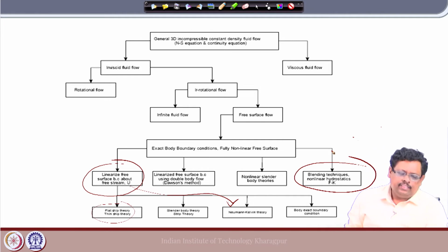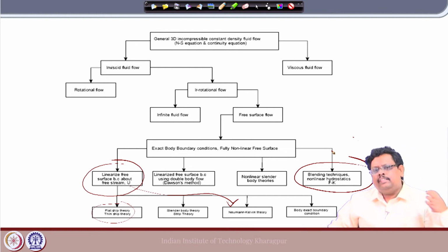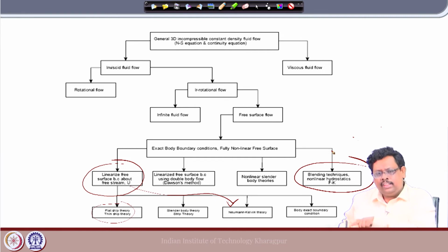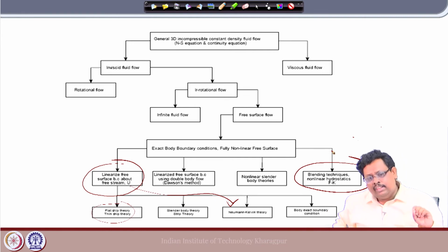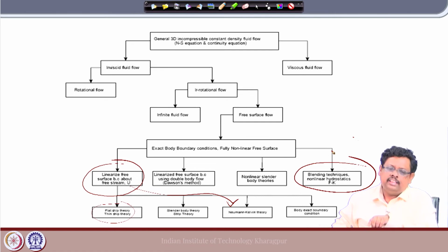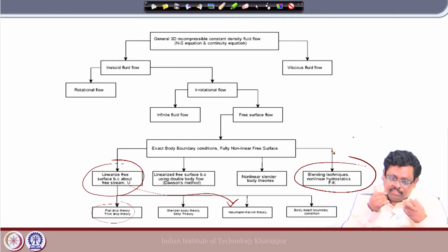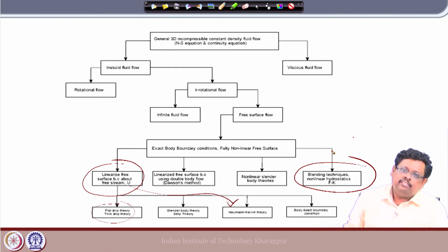So sometimes your software gives erroneous results, and that might represent weird physics. But since you do not have the knowledge of the limitations of the software, and when the software may go wrong, you keep on insisting on the wrong physics. And what is the outcome of that? Your design is faulty, and that is actually very dangerous, because the load you are calculating based on that particular physics may fail.